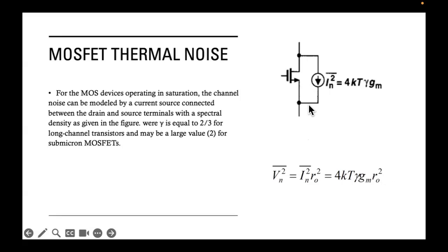Again, as we did for a resistance, it can be expressed either in terms of a current source, as you can see, or in terms of a voltage source, whichever is easier for circuit implementation.